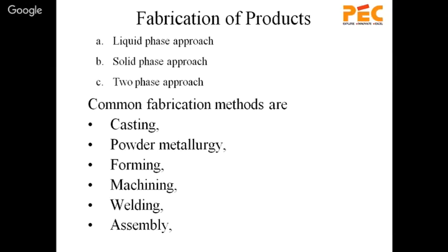That metal mold cavity also simultaneously requires a baking operation. Baking means you have to remove all the hydroxyls, which is very important, otherwise they will become oxides or gases, blowholes may occur and defects may occur in the casting. So after stirring you can put it into the prepared metal mold. The metal mold must have a clay coating and then baking, and then you put the molten material over here and allow it to solidify. So this becomes the process of composite casting.